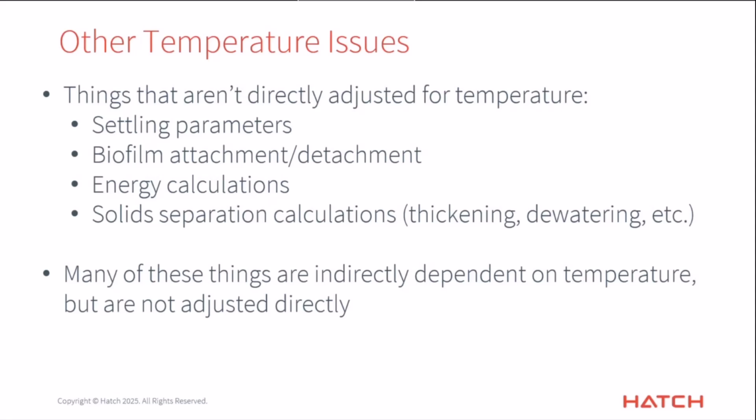A lot of the biofilm things that are there, like attachment and detachment, are not a function of temperature. The energy calculations are, of course, responding to changes in temperature, but they themselves are not temperature dependent. And pretty much all of our solid separation calculations, like when we're doing centrifuge and so on, are not really a function of temperature in any meaningful way.